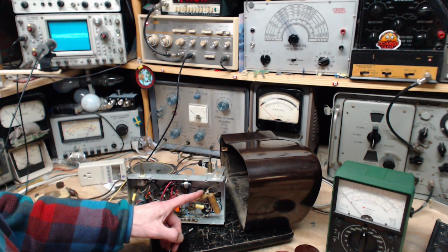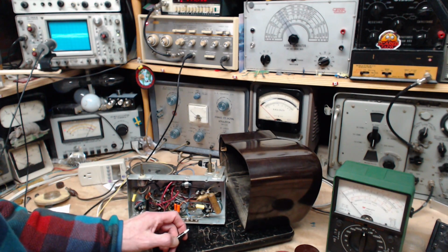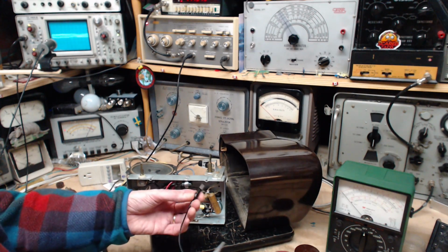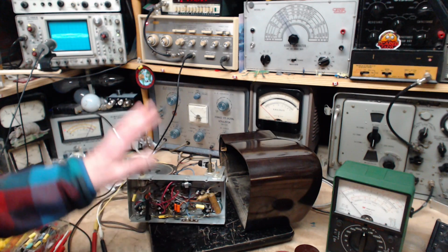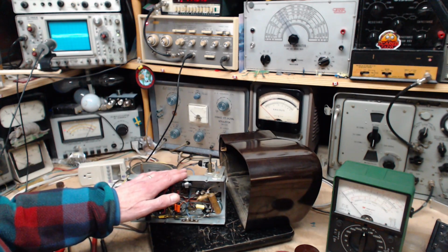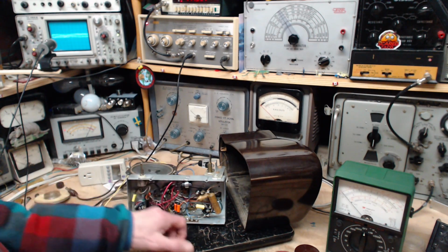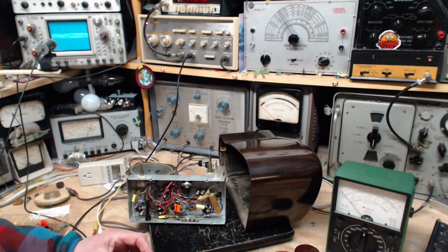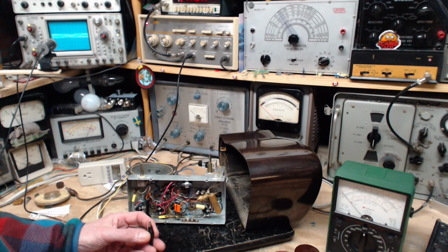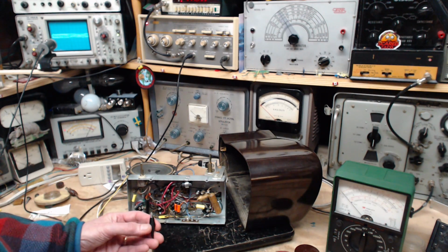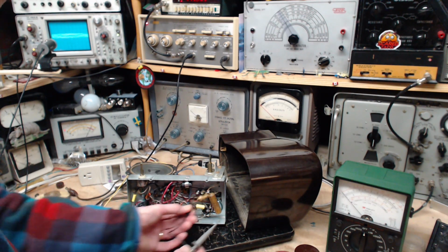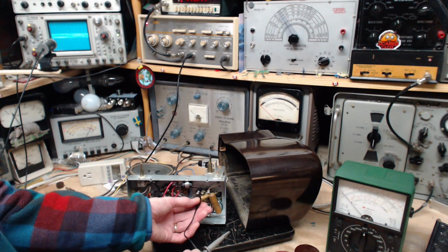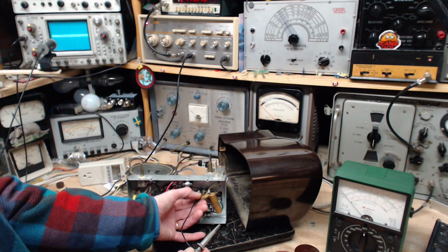So if this is not B minus, can I hook this up? What I'm pondering is, can I hook this up? This is being supplied by an isolation transformer, so I can put a ground on anywhere I want. One ground anywhere. Two grounds, no. One ground anywhere. I think I can probably do it. I can probably put a ground here. It would be no different than putting a ground like that. I wouldn't be too afraid to do that. Why would I be afraid to do this? It's the same thing. So put a ground there.